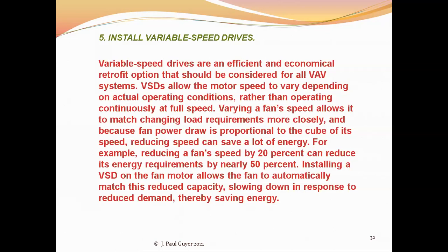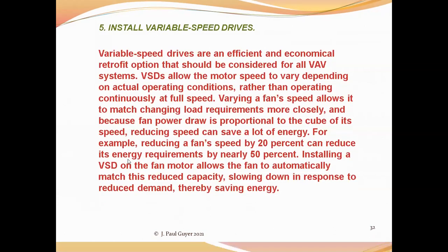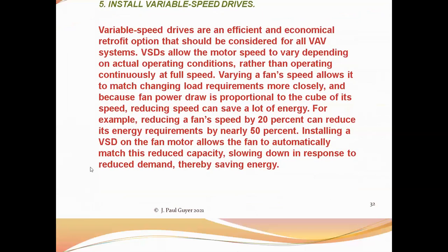And installing a variable speed drive on the fan motor allows the fan to automatically match this reduced capacity, slowing down in response to reduced demand. And there are significant opportunities for energy savings there.